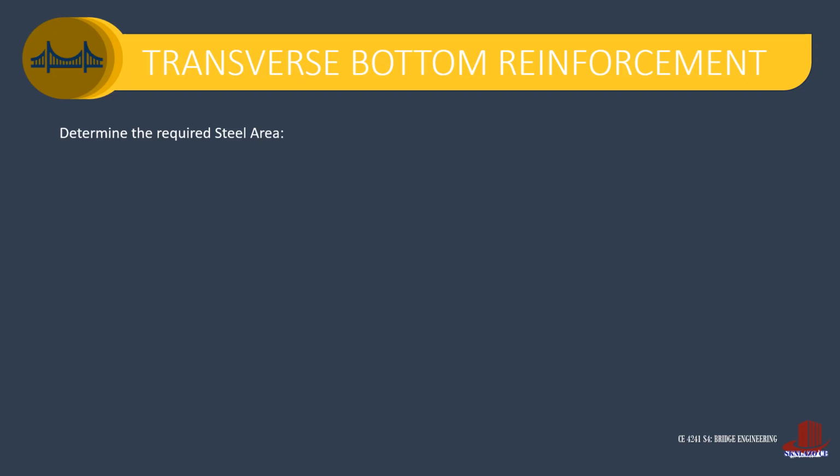We start the design with the main reinforcement, which is found at the bottom, along the width of the bridge. We are to look for the required steel area using the comparison of the ultimate moment from the loads to the nominal moment, taken from phi As Fy (d minus a over 2). Before we can solve As, we still need the block area a, from As Fy over 0.85 F'c times b, where we needed As again.